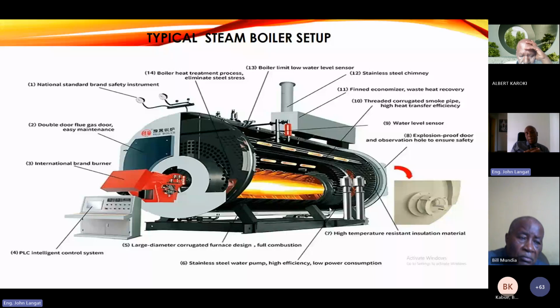So whenever you're auditing a steam boiler, if you find one pump is missing, then there's a risk, because this pump is overworked, which brings efficiency issues, and you're not supplying sufficient water into the boiler. Also, there is a risk factor. In case this pump fails and the other one is not operational, there's a likelihood that you may not be in a position to supply water to a boiler which is operational, which is quite risky, and the boiler might fail.